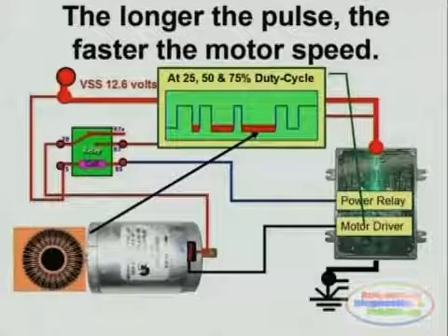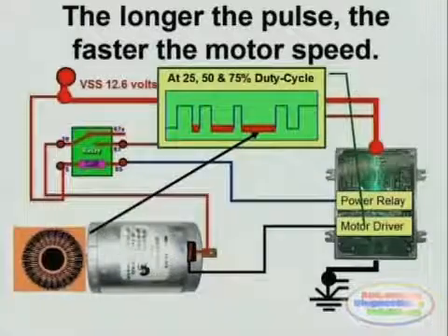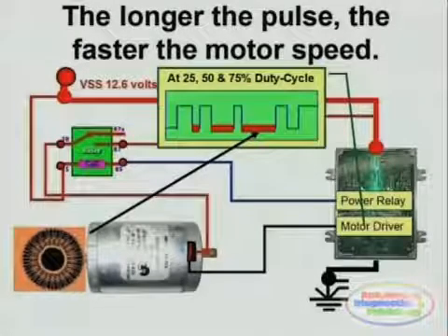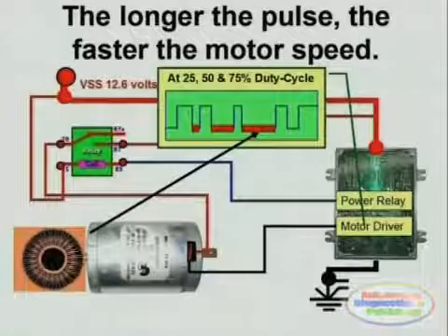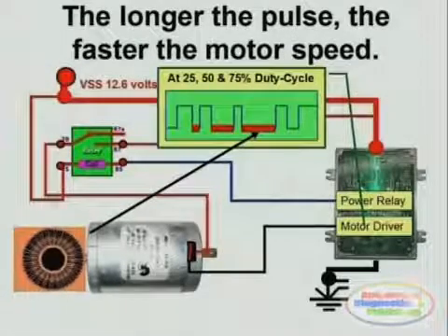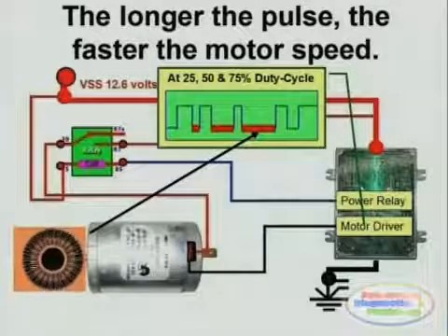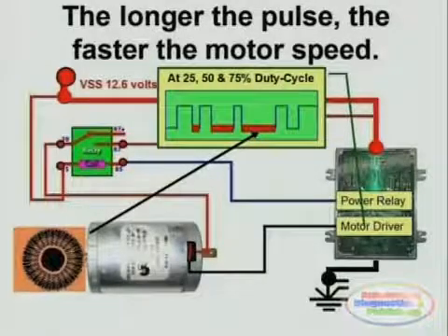For example, the newer types of fuel systems that do not have a return line rely heavily on fuel control by controlling the speed of the fuel pump, and this again is done through a duty cycle controlled signal.